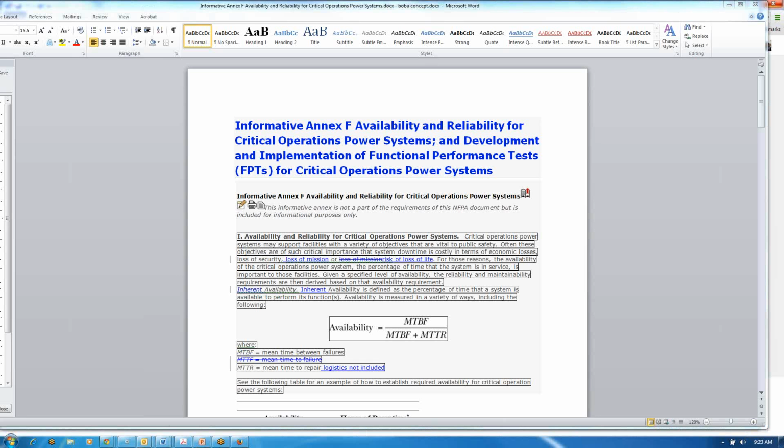feed from the same utility, which has its own transmission and distribution system. Right. Well, a lot of that is tied up to heat load, instrumentation, the degree to which you have a load shedding scheme. If there's a shared utility line, very often cogenerations have a shared utility line, and if your generation and your steam load don't match, you will drop a bus, so to say. So it's a very multidimensional problem, but instinctively what I think you just said is that it's probably wiser to invest more in your district energy system than your utility.